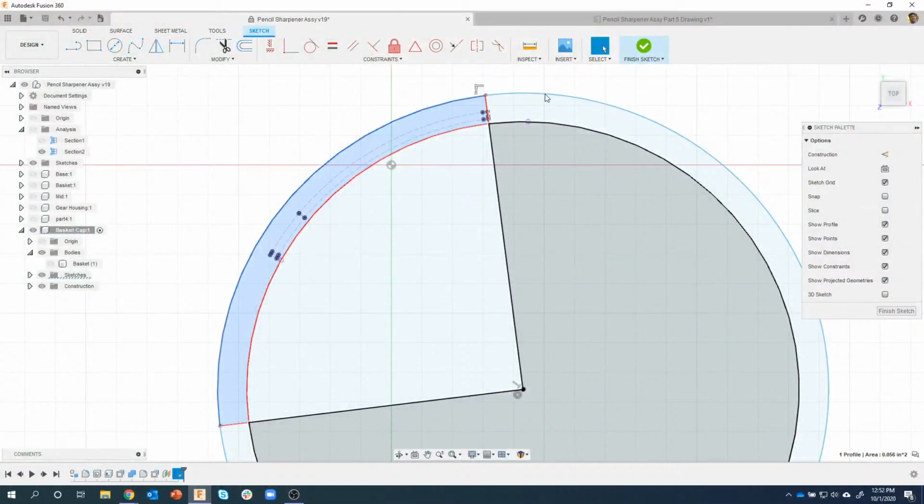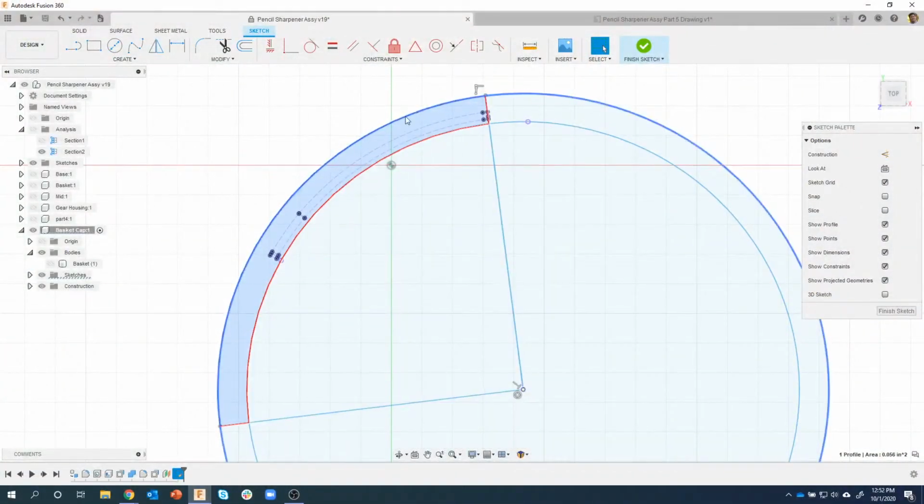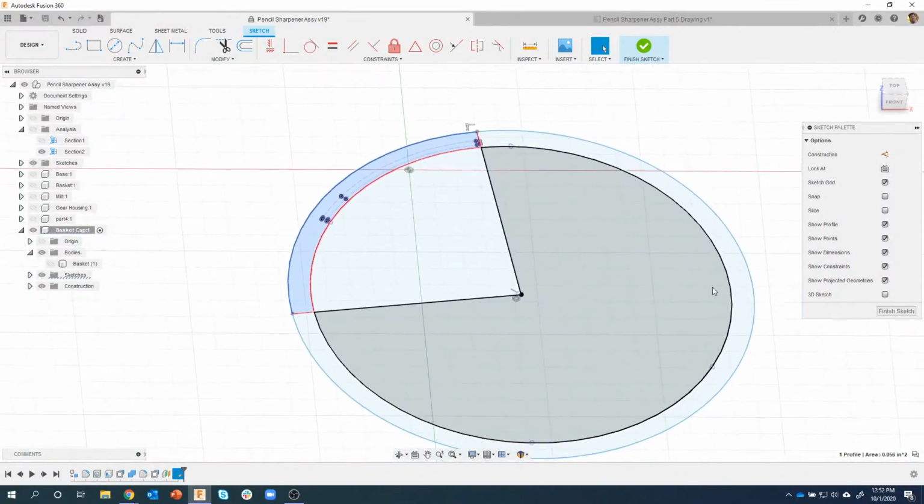Okay, so I know you guys love it when I trip and fall and try and recover, so hopefully the little tip there of, okay, let me confirm that my line totally touches this circle. And again, this is kind of why I captured to that point and then said extend, because I'm not guaranteed that we're in line with anything or whatever. So make sure that the software is doing the work for you instead of making assumptions. Okay, so I now have the profile that I want.